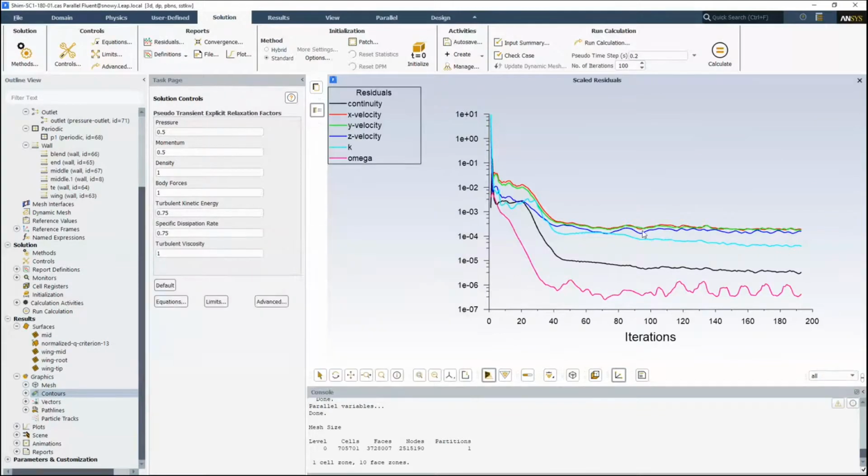We've dropped below e to the -3, so we've done quite well, but we can see we've got some transient behavior still being picked up, but that's okay because we've dropped below our certain criteria. So we want to have good convergence behavior, remember, because that's going to give us good adjoint convergence behavior, because adjoint uses the flow field solution, but it's a whole nother solution altogether.